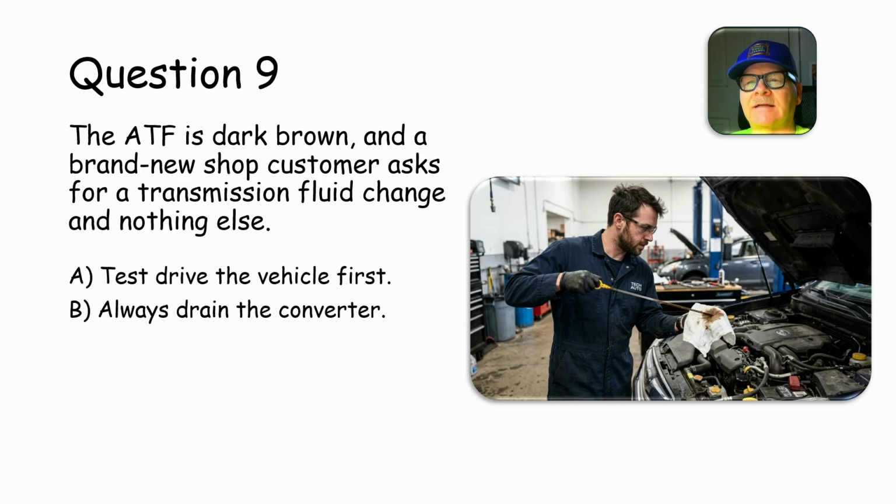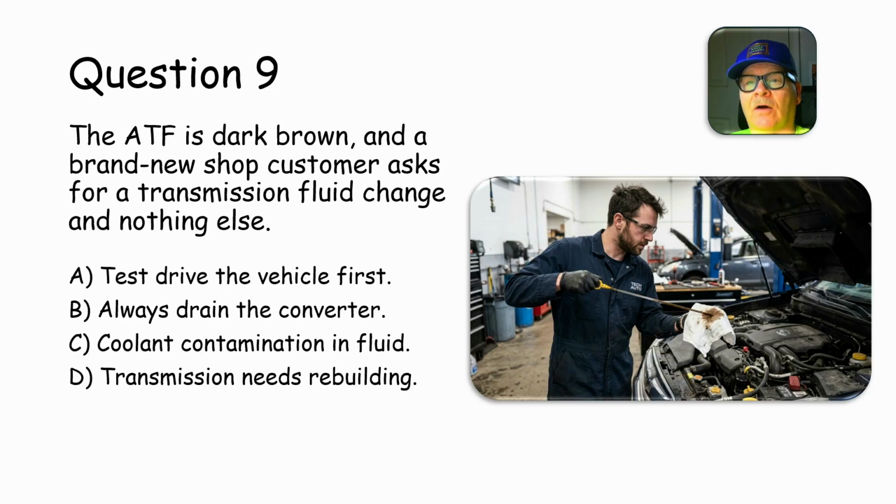Question 9. The ATF is dark brown, and a brand new shop customer asks for a transmission fluid change and nothing else. Test drive the vehicle first, drain the converter, coolant contamination in fluid, or the transmission needs to be rebuilt.